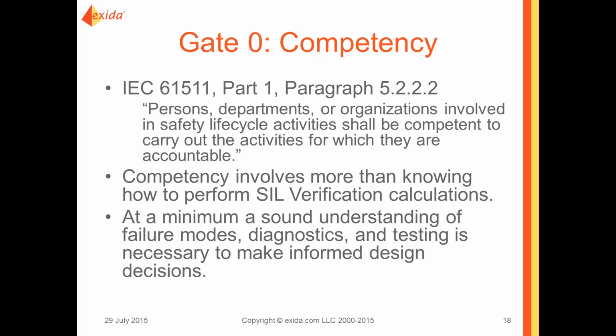So let's start with competency, and I've got that as gate 0 because you don't really get to start if you don't have the competency requirements in place. So 61511 clearly requires competency, and right from the standard, persons, departments, or organizations involved in safety lifecycle activities shall be competent to carry out the activities for which they are accountable. Sounds good. Competency involves more than just knowing how to perform SIL verification calculations.